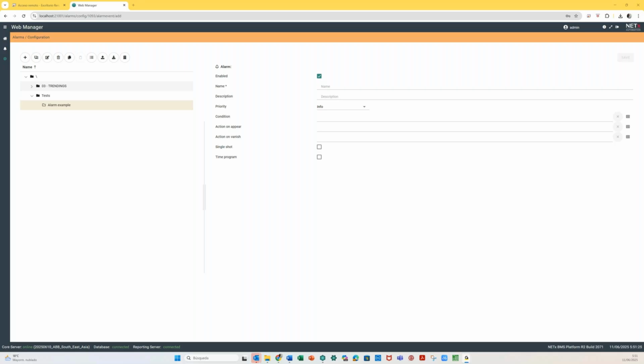So the BMS is really powerful to do this kind of comparison. Normally a chart is just representing these differences. But if you want the average, or the difference or calculation, just do this in a specific item, and just monitor if this value is above or below a threshold, and then the alarm will be done this way.